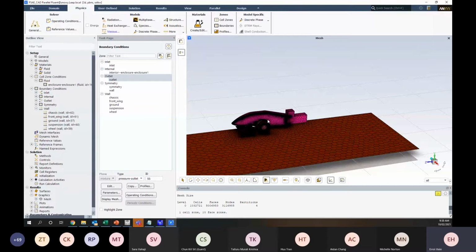I did a case recently where we did an atmospheric boundary layer, and that was specified using a log law function. Basically our velocity coming in was in the shape of something like this, because it's an atmospheric boundary layer, so 0 at the surface and increasing with increasing distance from the ground. And that's specified in the Australian standards as what turbulence values should be at what height. So yes, it can be specified, and also sometimes it might need to be calibrated as a trial and error method.